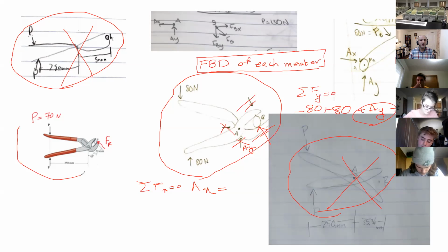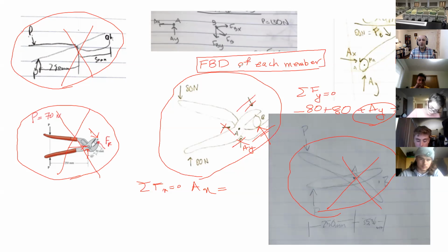Again, with this one, someone just tried to put one force here. If you want to do that, you're missing a whole bunch of other forces all over the place, right? So again, not isolated, not a free body diagram. Here's another one that I saw. If this is a machine or a frame, we draw a free body diagram of each member.